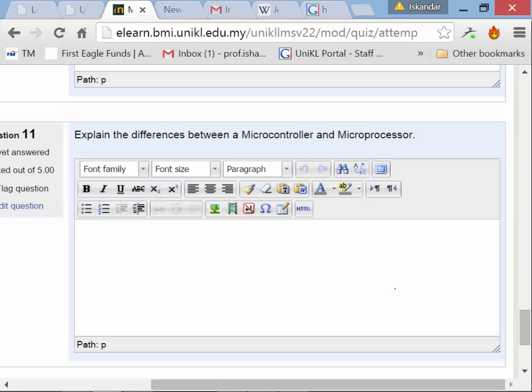If you look at the 8051, which we're using for the lab, what are we interfacing to that? Nothing, right? Just our inputs and our outputs. We don't have any external memory. We don't have an external clock. We don't have any external I/O interfacing out there. It's all built into the chip right there.